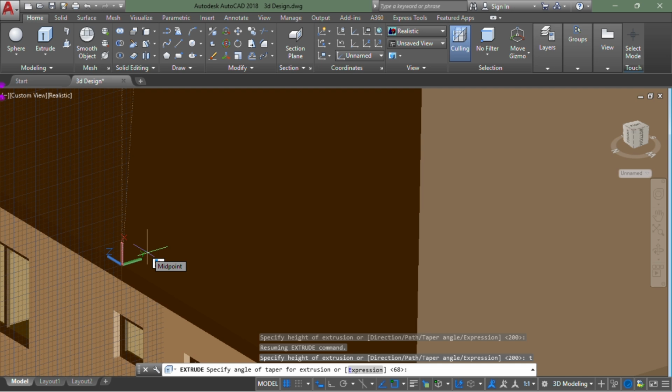And when we were doing our 2D design, I explained earlier that for our roof plan design, we'll be using 45 degrees, right? But when it comes to our elevation and 3D aspect, then we'll be using between 15 to 30 degrees, right? So as not to make our roof too high, all right? So this time around, we're using 22 degrees, right? For our horizontal pitch angle.